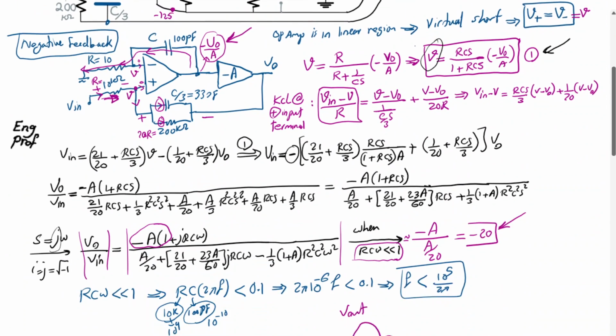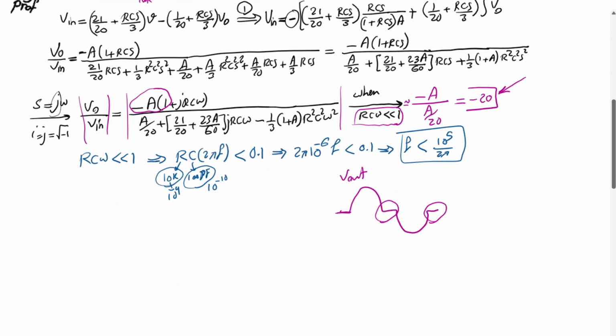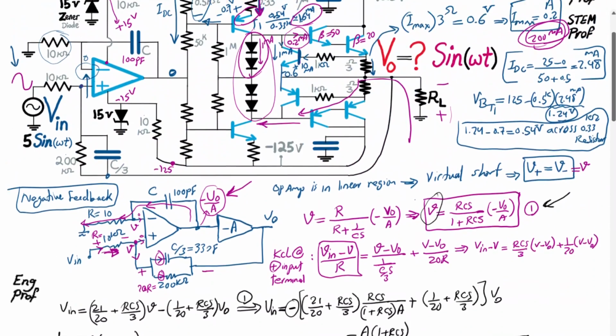Then, instead of this circuit, we have a near perfect Vout without dead zones. It was basically a zero crossing issue. These zero crossing problems, dead zones, are avoided with the proper biasing.